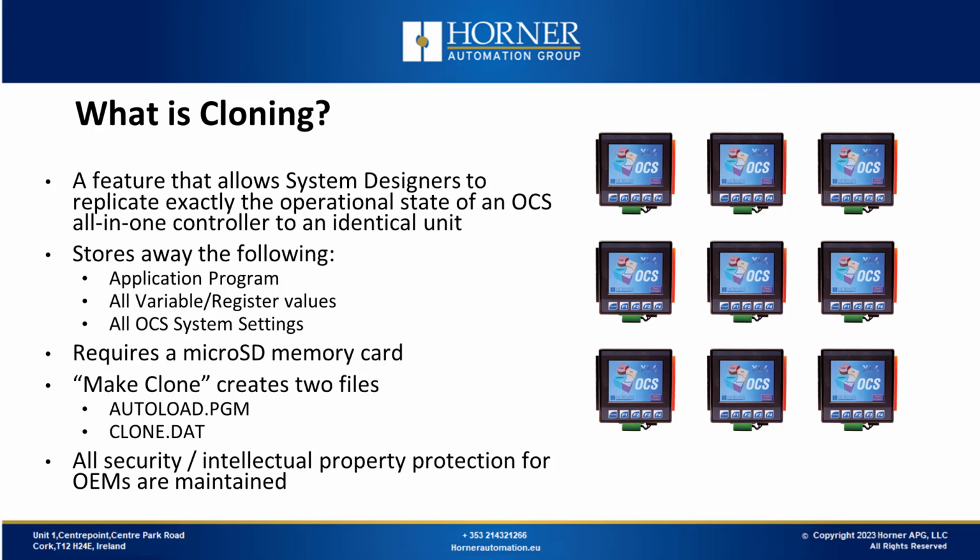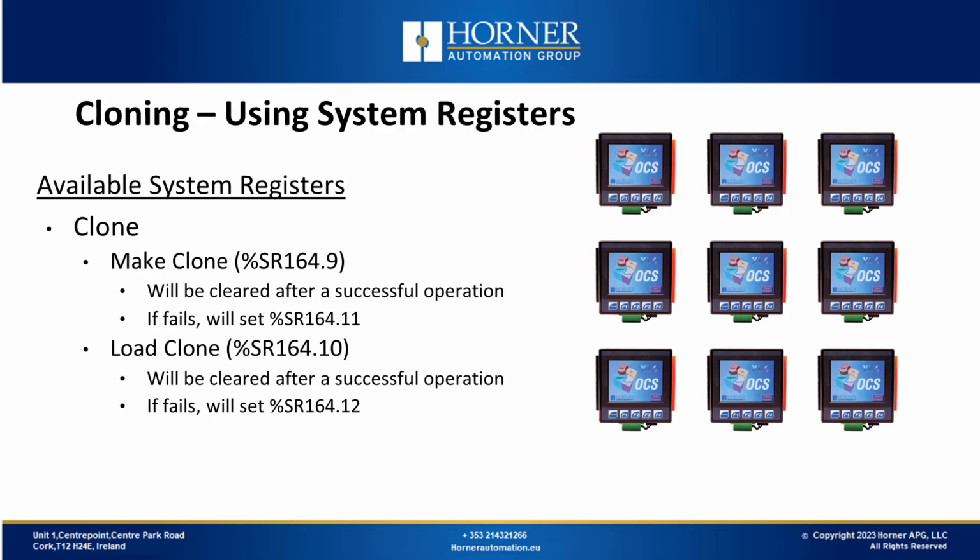It's worth noting, if you have security enabled in Cscape to safeguard your intellectual property, unauthorized users won't be able to load a clone without the appropriate authority. The system will prompt for a password, adding an additional layer of protection against unauthorized cloning and potential intellectual property theft. And once again, you can do cloning from system registers, even though it's a little less common, it's still possible. There are system bits available for that function.